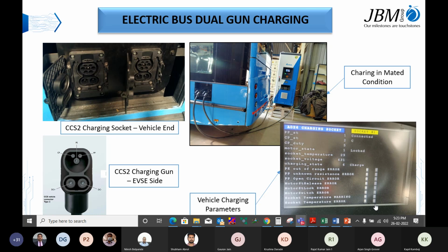Okay, got it. And the second thing you mentioned is that while charging, it checks the IR value up to 750. While it checks the high voltage current, it sends the high voltage value, right? 750, approximately 700, you told me, right? Yeah, up to 700. As per the charger: the Exicom charger we have gives up to 700 V cable check voltage. The Delta charger we have gives 400 V cable check voltage.